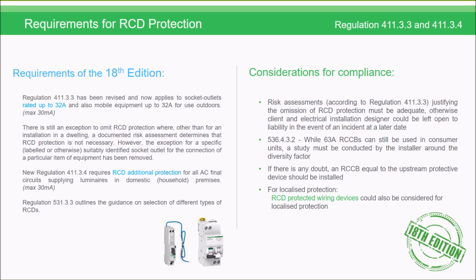So just coming back to a few points here then, is that the risk assessment according to Regulation 411.3.3, and this is to justify the omission of RCD protection, it must be adequate. Otherwise the client and the electrical installation designer could be left open in terms of liability in the event of an incident at a later date.